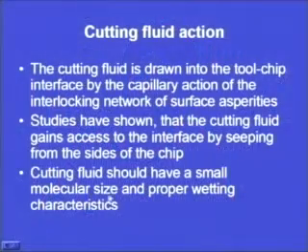Then the cutting fluid should have a small molecular size and proper wetting characteristics. Whatever surface asperities we are talking about, or whatever zone the cutting fluid has to go into, the size is relatively small. So, for that action to take place, the molecular size of the cutting fluid should be small, and it should have proper wetting characteristics.